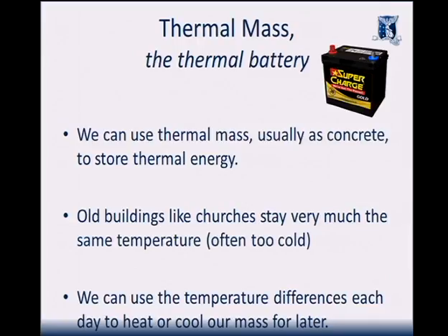Typically concrete is used, but there are other elements like water that store temperature. So if you're in a high thermal mass building, it won't vary in temperature much.